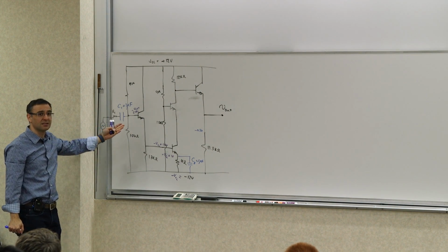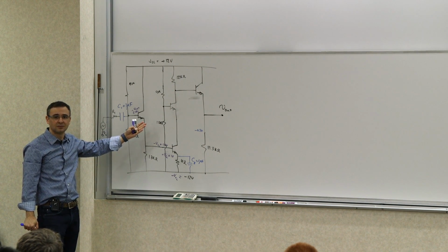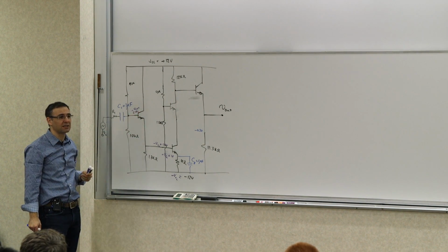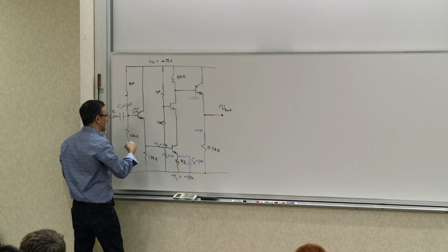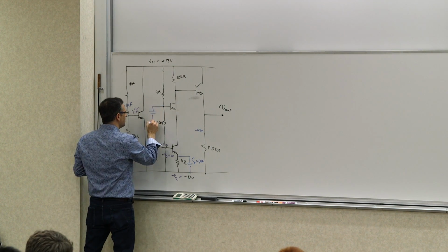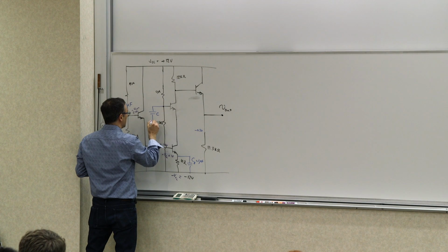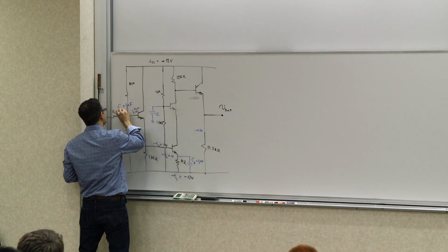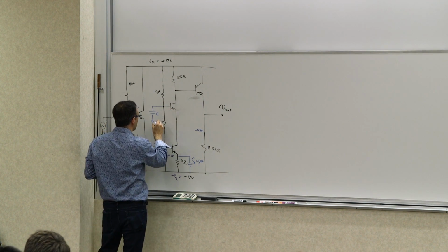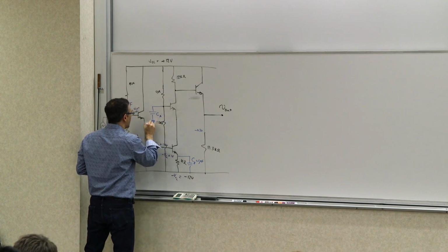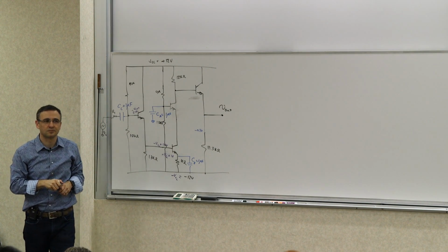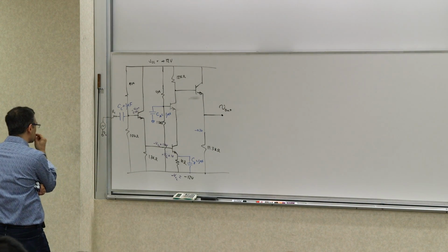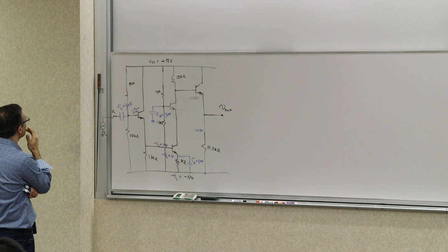How do I make it...? But I need those resistors to establish the DC level. So how do we make it, from an AC perspective, a ground? Another reactive element, right? What should I use? A capacitor to ground. Let's call this CC, CB, I don't know, CA. Let's make that 1 microfarad.